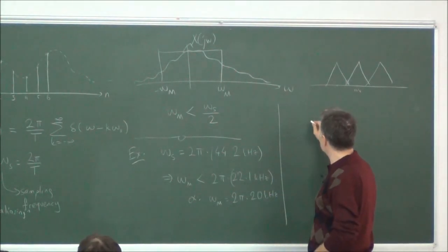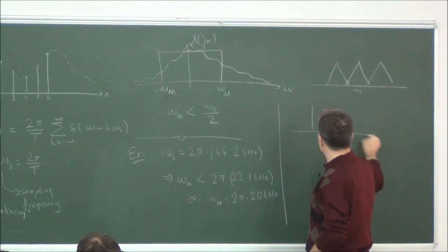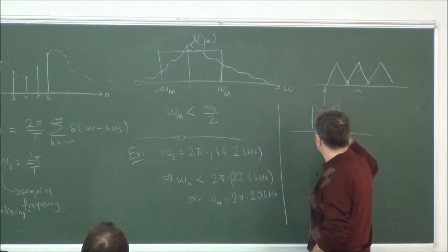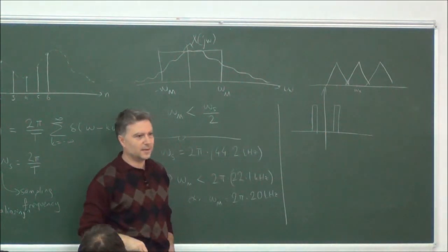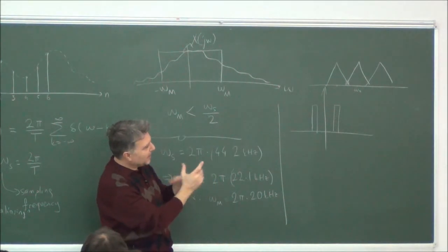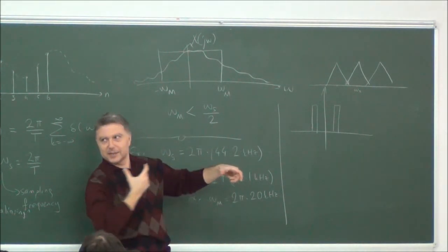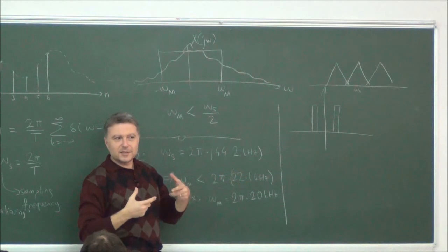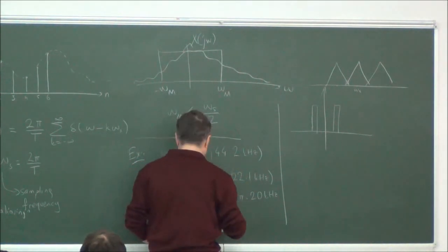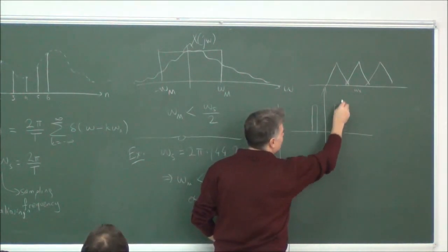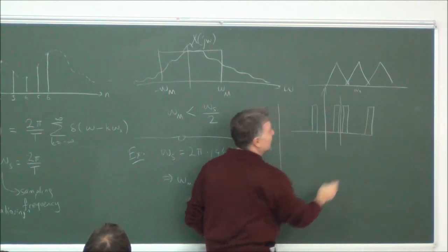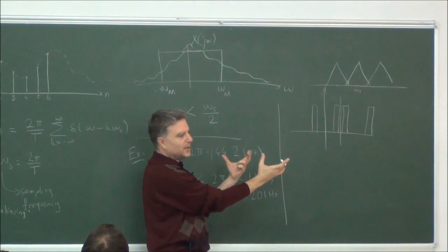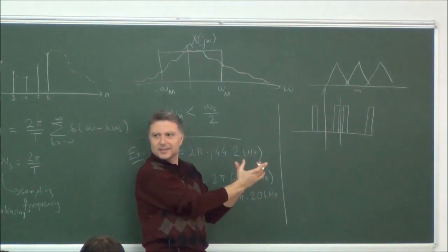The situation is like this. If your signal is not low pass but band pass like this, then by replicating towards right and replicating towards left, it is not only required that your next reconstruction starts from here and here, for example, the right hand side replica. It may be even inside still.